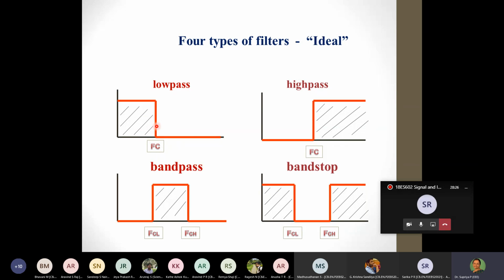This removal of higher frequencies is what has been shown here, usually called the brick wall response of a filter, perhaps you remember it, wherein we assume that the magnitude of the filter is 1, which could naturally be changed depending upon the application, but in an ideal case a filter will have a magnitude of 1 and it will allow all frequencies up to that cutoff frequency which you are choosing to pass through.